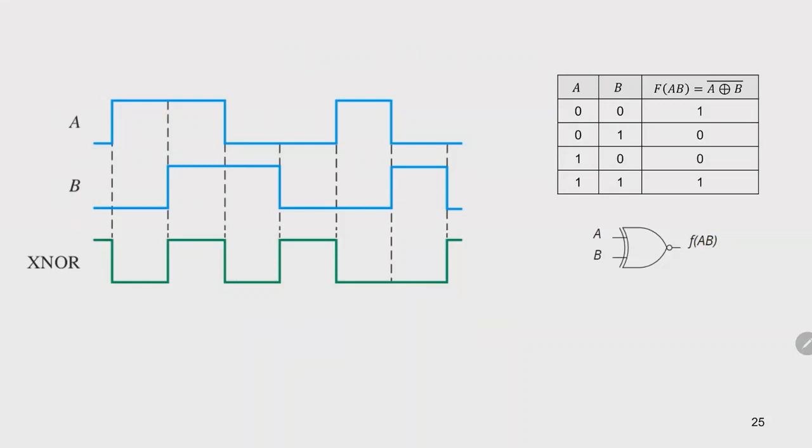So for example, the previous circuit that we have just now is the exclusive NOR gate. If my A input changes in this fashion, and my B input changes like this, then my output will be changing with time as well. And how do you work out the outputs in a timing diagram? One way to do it is to write down the logic of the waveform.